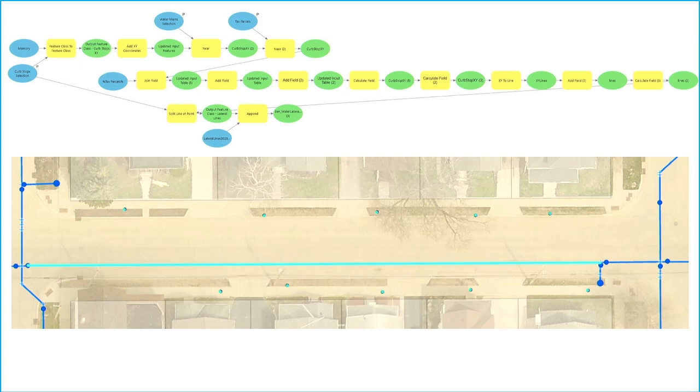So similar concept, I'm saying from this point, I want to draw a line to the nearest main. So actually, I can't read it from here, but there should be the near table somewhere in here. It looks like I'm using near here, but again, I'm exporting the data over here. Feature class to feature class, I believe, is getting deprecated, so export features would be its replacement if you needed to.